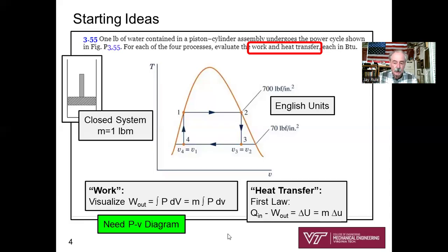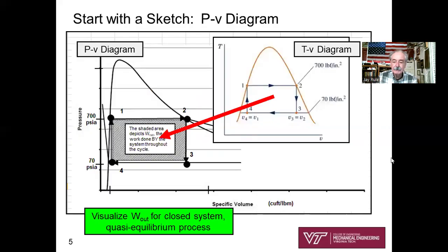Now let's plan our work sort of in detail. Well, let us draw our pressure volume diagram with the vapor dome and translate this cycle over to here. Well, we see we're going to start at 1, saturated liquid. Okay, there's 1. 2, constant temperature, saturated vapor. Okay, so remember, under the dome, the pressure and the temperature are dependent variables. That's how we know. That's also a horizontal line on a PV diagram.